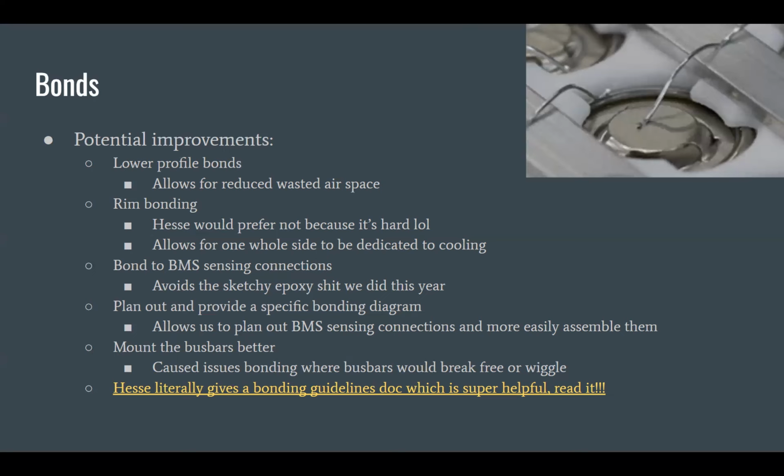Then as they try to bond it, since it's ultrasonic, it'll actually vibrate up and down. Because it's vibrating, it's not generating the heat that they want to generate, and it's not making good contact. So they'll try to bond and it just spaghetti noodles up into the air. I think you can see a video on their Instagram of bonding our pack. I didn't look, but they asked me for permission, and I said yes. So if you find the Hess Mechatronics Instagram, there might be a video of our pack getting bonded. Because they asked, and I said sure.